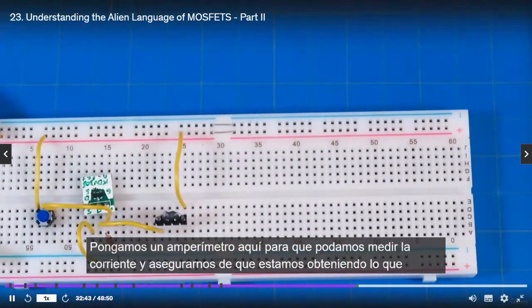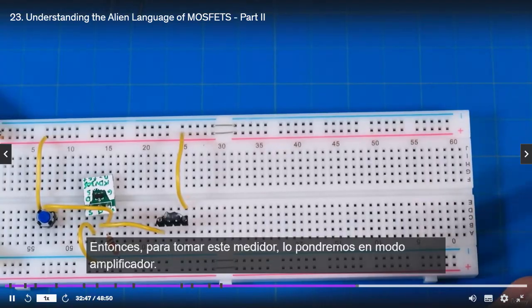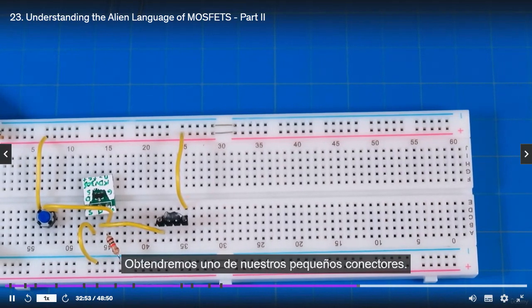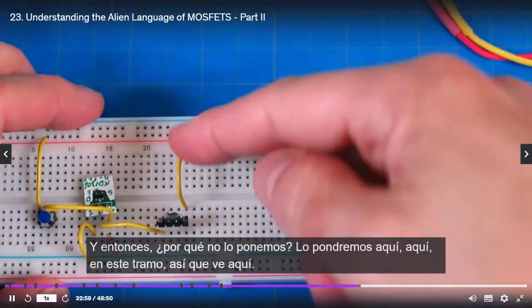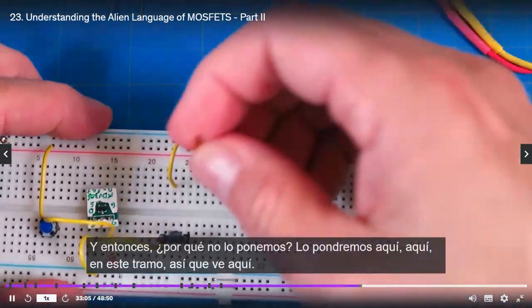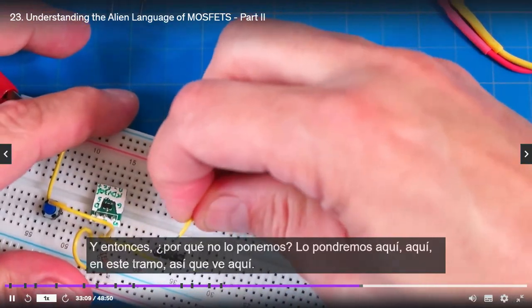Let's put an ammeter in here so we can measure the current and make sure we're getting what we think we're getting. So we'll take this meter, we'll put it into amp mode. We'll get one of our little connectors. All right, and then we'll put it right here in this leg. So go right here.